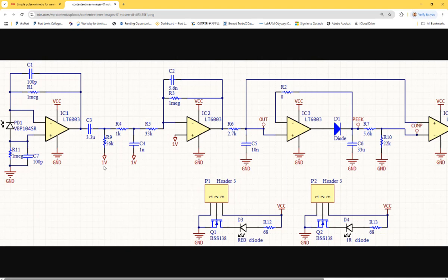That's the DC offset. Okay. Apply superposition. Keep in mind, I have told you guys, I've gone through superposition multiple times in both classes, right? So with superposition, that DC signal will be directly added to the output node. You get an AC swing after the high pass filter, and the original arbitrary DC signal will be filtered. It will be gone. We don't like it because you don't know what that will be. A different person will give you a different DC offset, and that makes it super difficult to predict. So eventually, we use the high pass filter to remove that arbitrary DC offset.